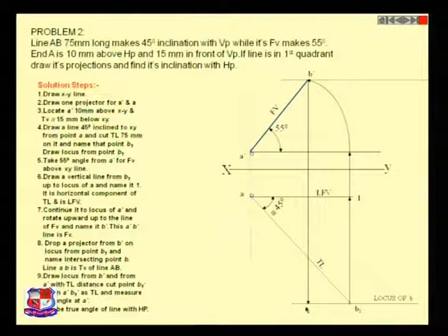Take direct projection from this front view and you can get your top view like this. As you all know that front view and top view will always be in one line, which means that top view lies like this.